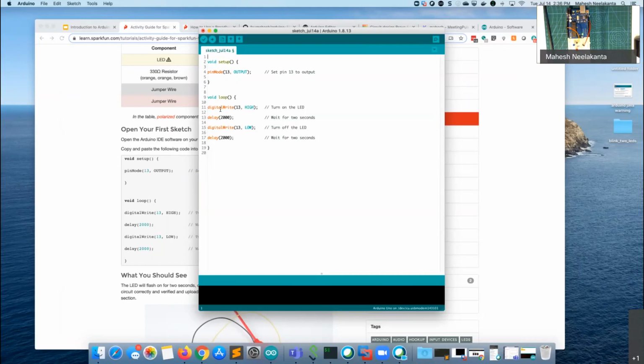So the first thing, as you remember, we connected to pin 13. And what this does is it says, hey, configure this pin to send electricity out. In other words, go in output mode. Input means read a value. So for example, if you're reading temperatures and things like that, you would get data and you'd configure this for input mode. And that's all we're configuring it for.